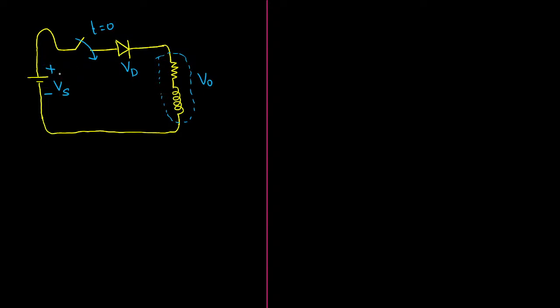One thing you have to understand is, once again, first analyze the diode. The positive polarity of the supply is connected to the anode the moment we close the switch, and the negative of the supply will be connected to the cathode terminal. Definitely this diode will turn on and it will be short circuited. Once it is short circuited, you can observe it is the DC supply with the RL circuit. Definitely what you can observe is an RL transient circuit.